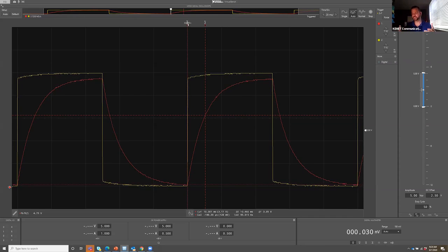There's a little bit of variation here because of tolerance, because this is a non-ideal circuit, and there's other things that are not being taken into account. But generally, yes, that's what happens. So those of you that mentioned that the output of this circuit is going to be shark fins, in the red, you can sort of see those shark fins rising and falling with a bit of a delay to what the original input was. Now, those of you that said that it depends on frequency, you're also right.